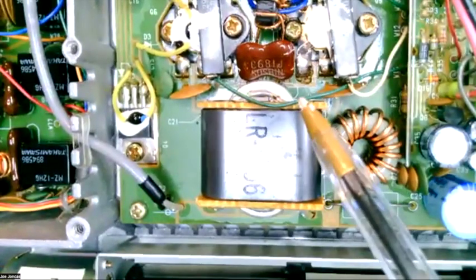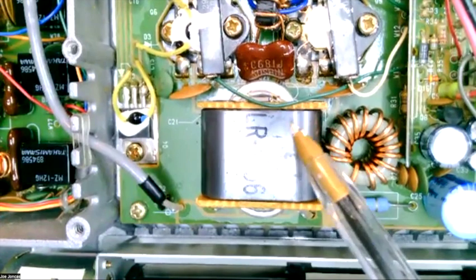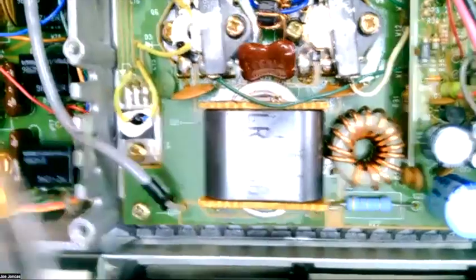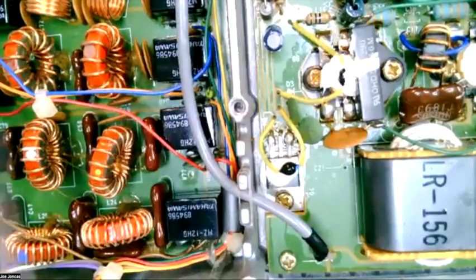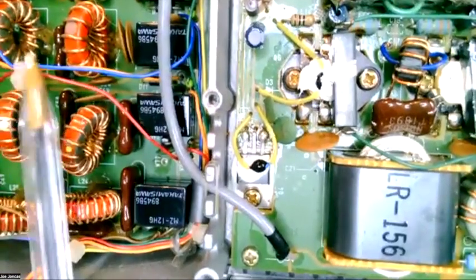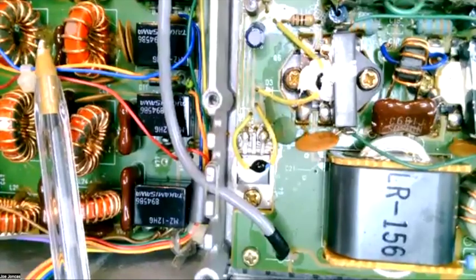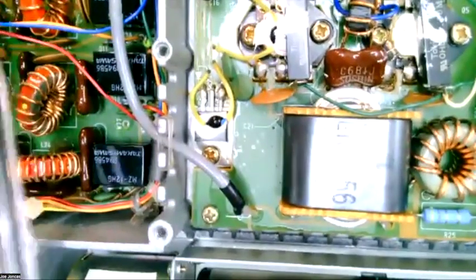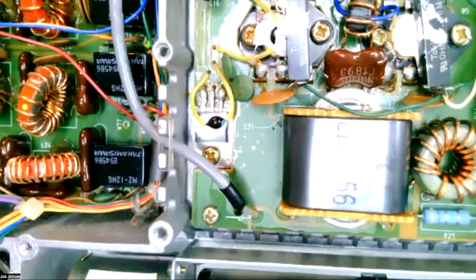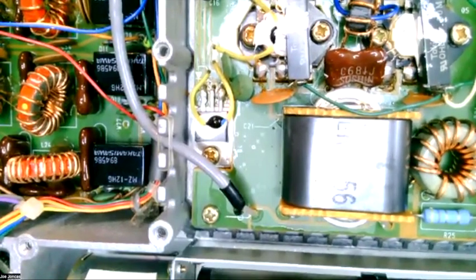But what happens is an amplifier can generate secondary signals that will go out to the antenna if you don't have something like this to filter it. So on transmit, you want the filter to keep from sending out unwanted signal. And on receive, you want to keep unwanted signals out of the radio, which will interfere with how it works. And then, of course, here's a fan, which blows across everything.